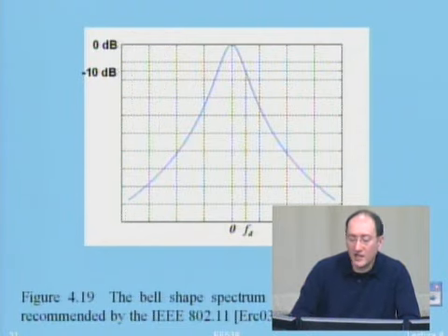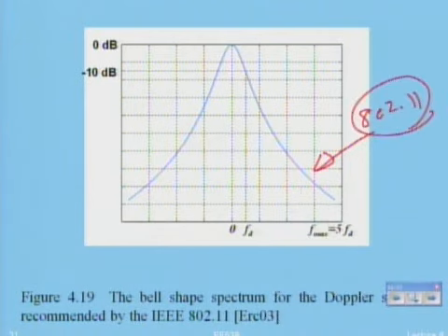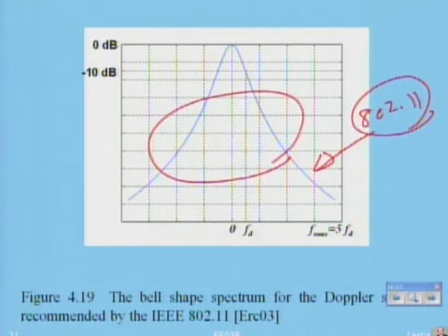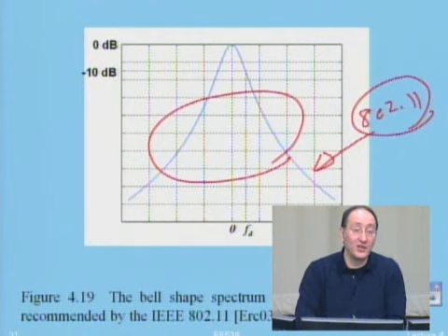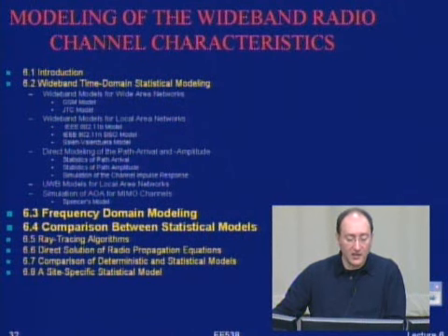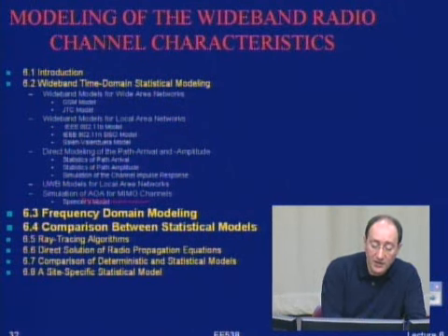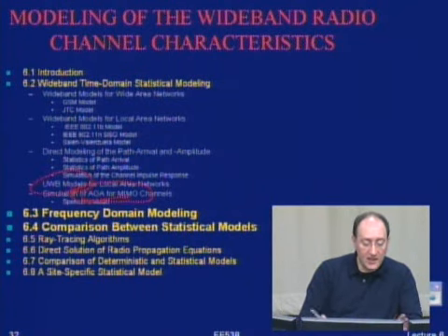Now, this is like the delay power spectrum. We have talked about that. I mean, in 802.11, they are using like this function for delay power spectrum. Okay? Which is like a bell shape or like a low-pass filter shape. It's easy to implement, and it's consistent with what? With like measurements that Steve, for example, had done, and I had shown you earlier. So that was about like simulation of angle of arrival for MIMO and simulation for ultra-wideband. I talked a little bit about that.